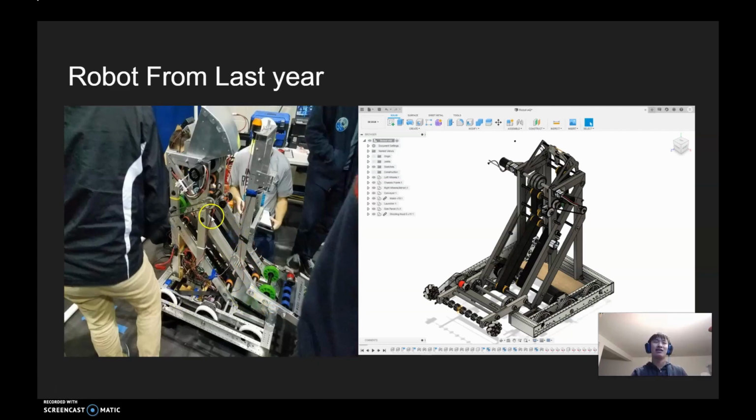So this, near the motor and sprockets and chains, is dangerous. This, potentially dangerous. Alright, so you want to keep wires as close to whatever frame structure they're attached to as possible, maybe even inside or within tubing and away from moving parts. Alright, so that is more electrical, but anyways, that is something wrong.